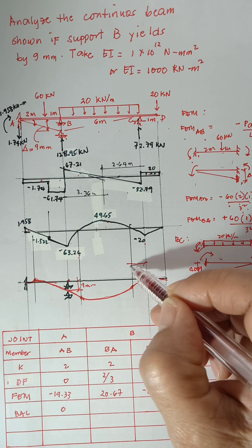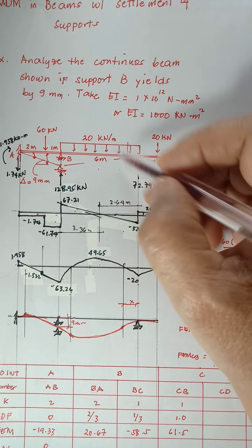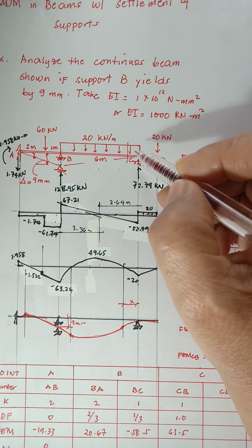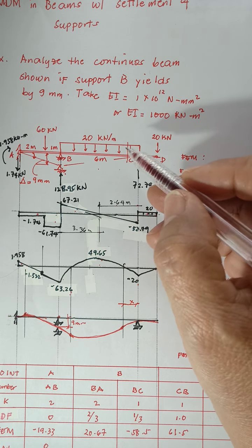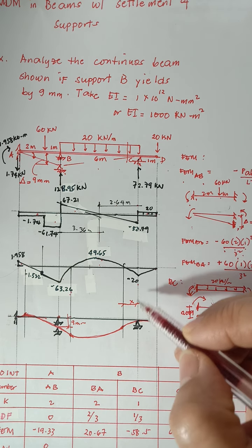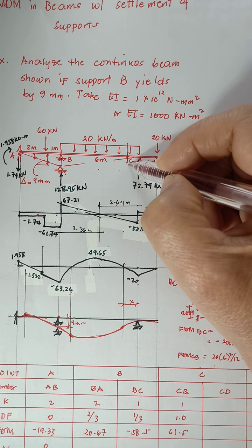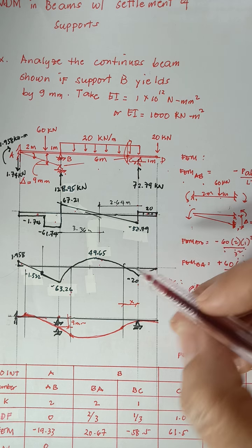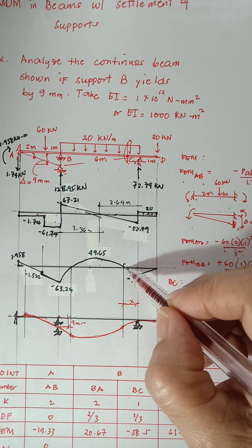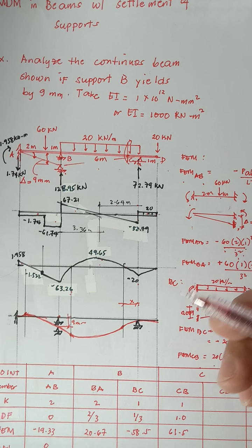Consider this as X and project it up, then cut that section. You have your free body diagram. You can consider either the left section or the right section, and consider that as X. You solve for the shear and the moment at this section, and equate the moment to 0, so that you can solve for x.